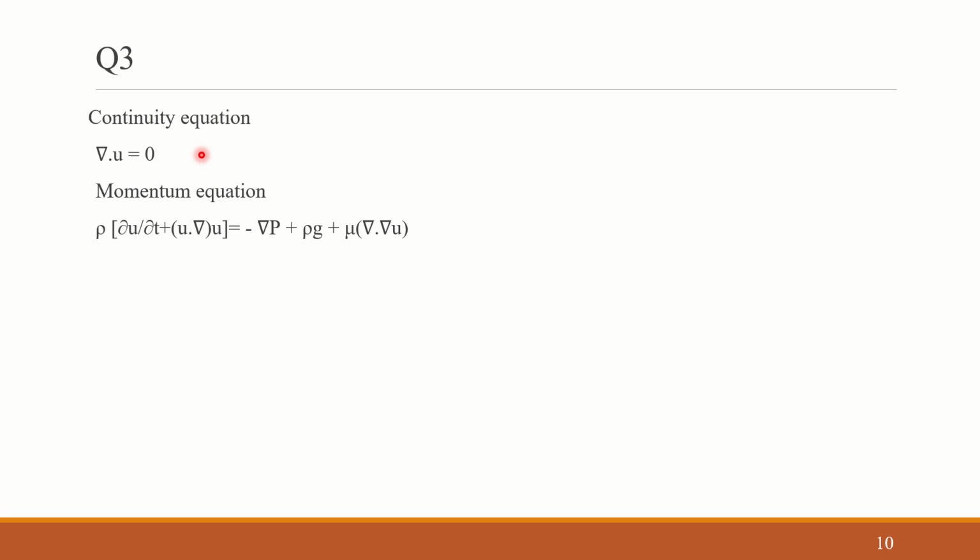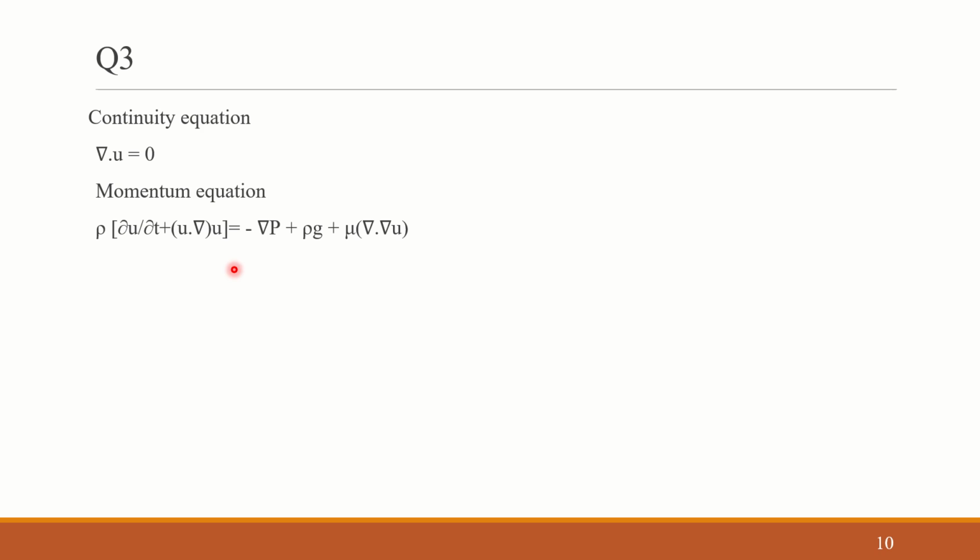and it is a steady flow, laminar flow. So on that basis we are cancelling out the LHS terms, and also here we are not considering the body force. So it is minus delta p plus mu into del dot del u equal to 0, where p is the pressure gradient force, mu is the viscosity and u is the vector component of the velocity. So that is how we obtain the equation.